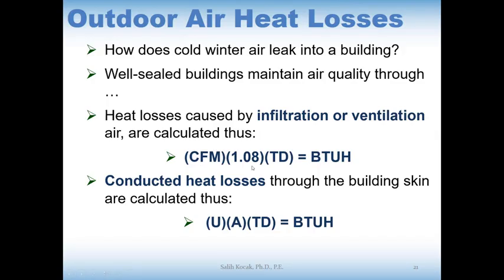So 6,000 times 1.08 times 70. And this is going to be 453,600 BTUH.